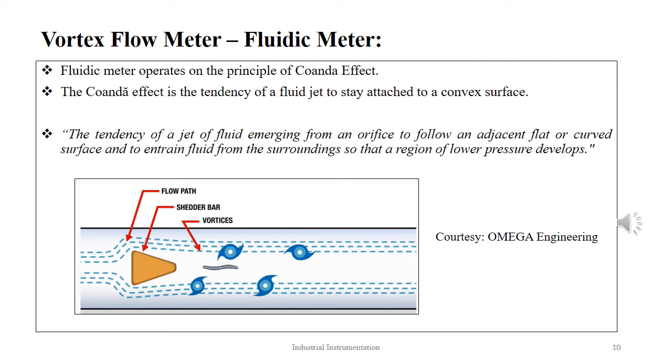The second method is the feedback oscillator system, in which the deflected jet causes a low pressure area at the central port. At the upstream feedback passage, the pressure is higher due to a combination of the jet expanding and stagnation pressure. Thus, a small portion of the main stream of fluid is diverted through the feedback passage to the control port.